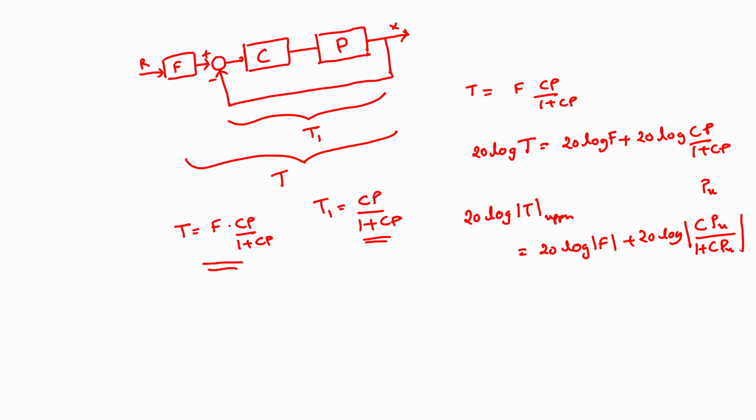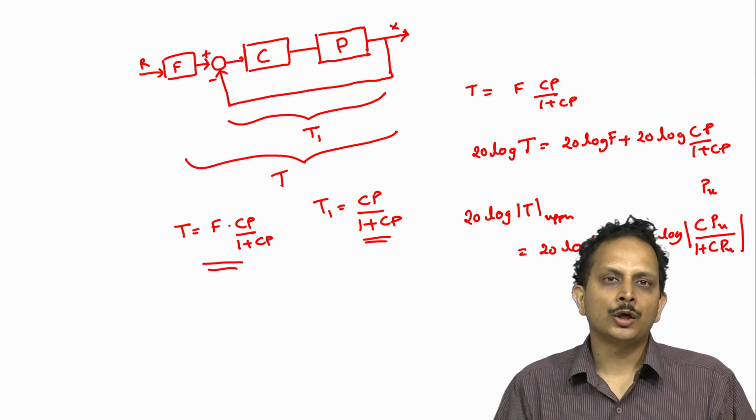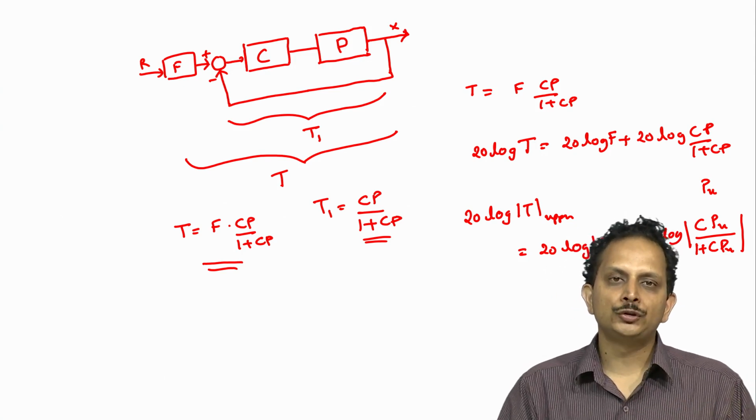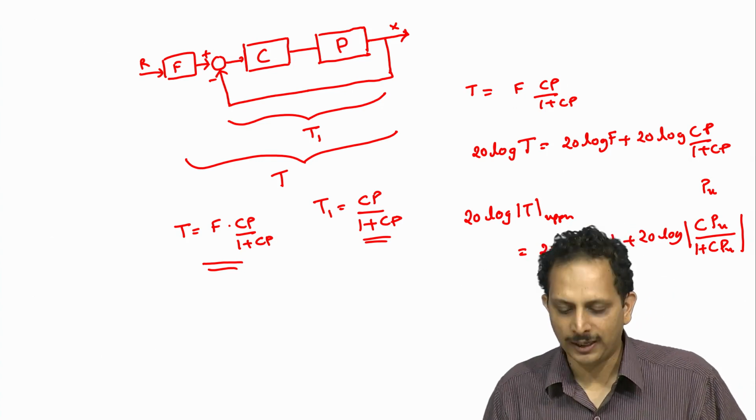So this is the equation that would relate the transmission function T upper to a particular structure of the plant that gives us the transmission function T upper. Likewise, there will be another combination of parameters of the plant, namely its uncertain gain and its pole location, that will result in the overall transmission function assuming the value T lower at a particular frequency omega.